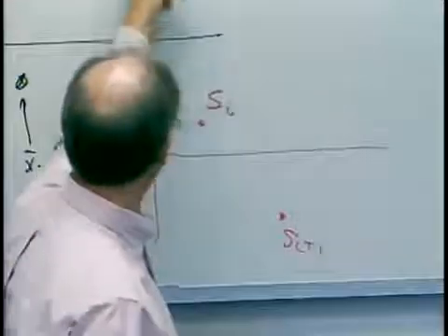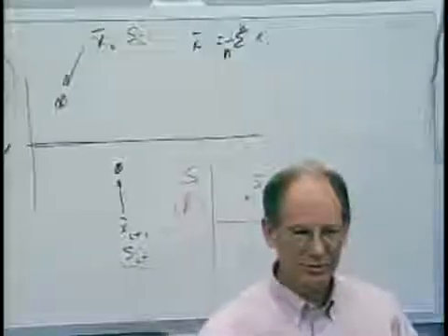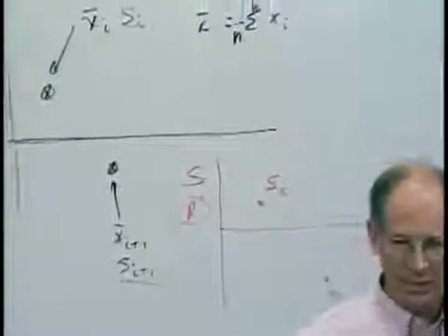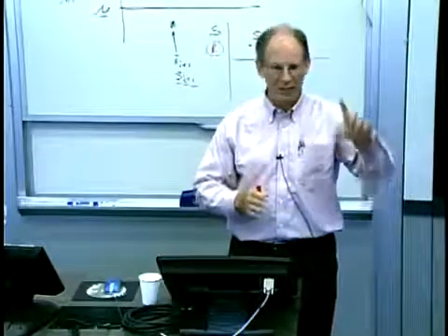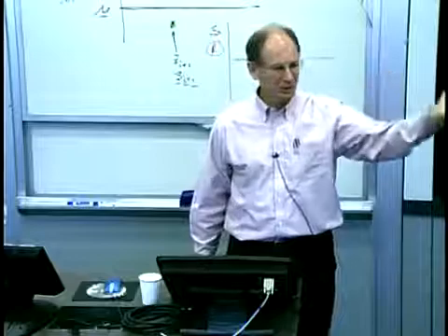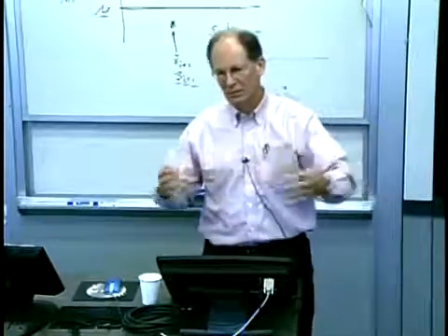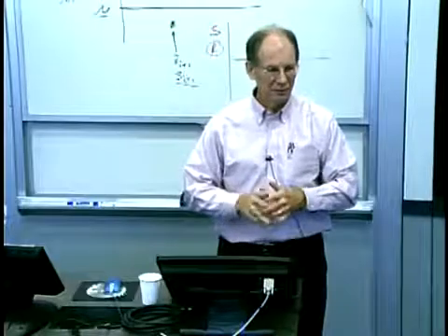Especially if, let's assume n is a number like 5. I'm taking 5 samples, plotting data, making decisions on a factory floor. Why would I use range, which just involves a subtraction of a minimum and maximum number, versus standard deviation, which is, you know, sum of the squares and all that other stuff? Why would anybody ever want to use range?